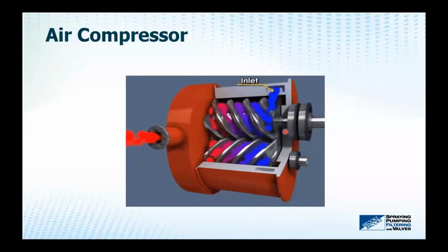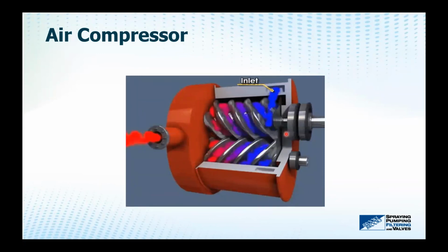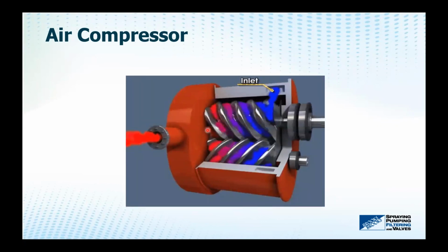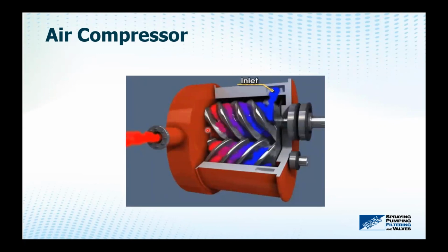Basically what occurs is that you're concentrating the contaminants, the water load, the chemicals, the hydrocarbons sevenfold, because you're taking air from an atmospheric pressure of 14.7 psi and compressing it to 100 psi. So that's approximately a factor of sevenfold. So the concentration increases of your dirt, your acids, hydrocarbons. But since the air is warm, it can hold more moisture in it.